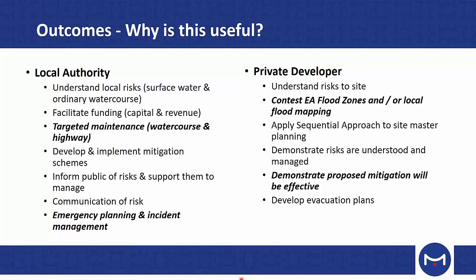For private developers, this type of modelling helps them contest EA flood zones or local flood mapping. Often the local flood mapping that's been done is very high level and can be of low accuracy in some areas. So this kind of detailed study helps develop a much more detailed understanding of what's going on and practically manage risk within sites, and you can open up larger parts of development sites by demonstrating the risk is different from what the national mapping says or can be managed more effectively.